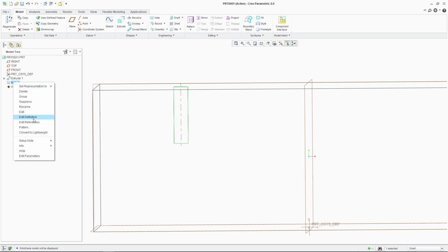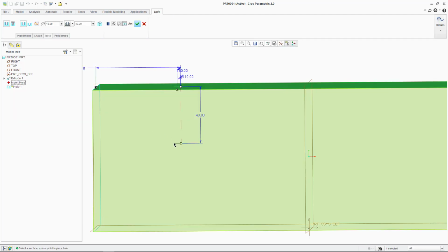But let's say you did want a hole which represented a drilled hole with a standard drill with, say, an angle of 118 on the end. Well, we can select this option here, and whereas currently we're using this, use predefined rectangle as drill hole profile, this changes it to use standard hole profile as drill profile.